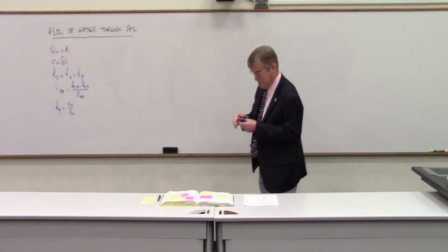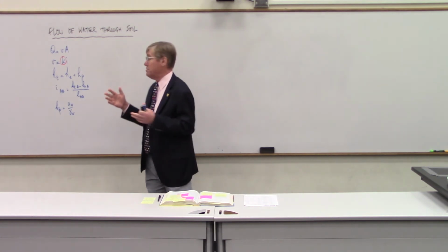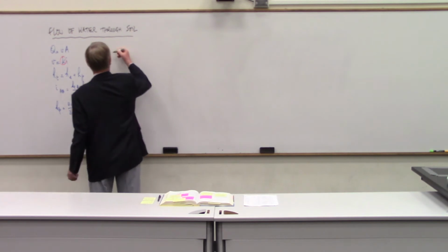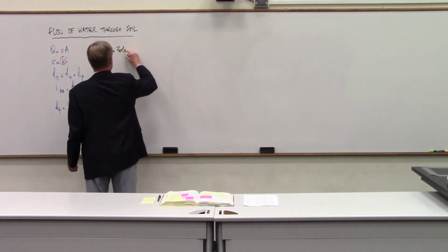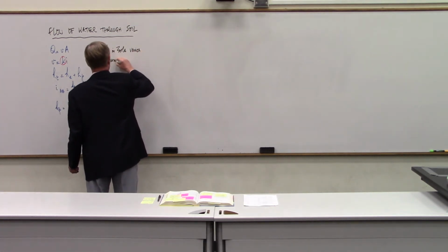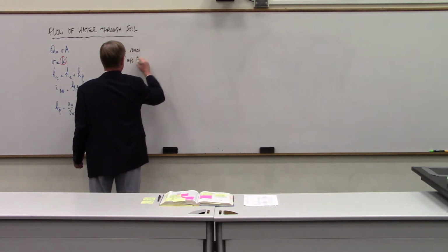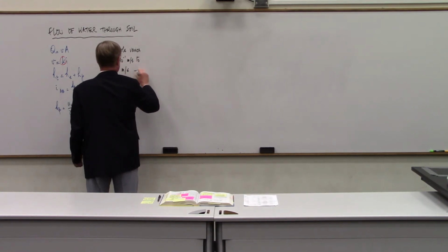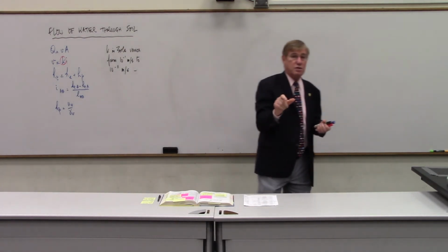All right, so how do we measure? We don't have the same test because K varies so much. K in soils varies from 10 to the minus 1 meter per second to 10 to the minus 11 meters per second. So 10 to the minus 11 meters per second, I don't know, it's a few centimeters per year.